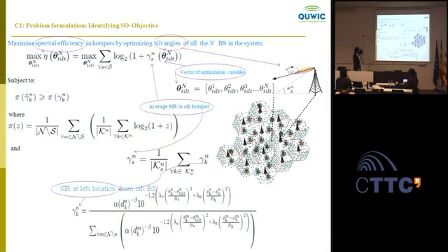This eta here is spectral efficiency, which is a function of the vector of tilt angles for all the antennas in the system. And we want to maximize the spectral efficiency. That's why we don't have bandwidth here, which is theoretical, you can say, ergodic capacity without bandwidth, normalized capacity. And this optimization has to be done over this vector, which is n. And n is as large as the number of antennas in the system. For example, if you have 2000 antennas, you have 2000 parameters.